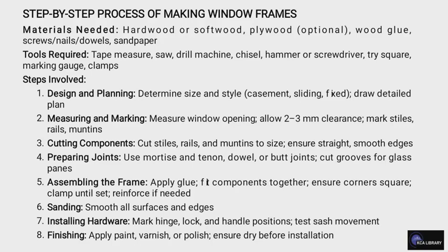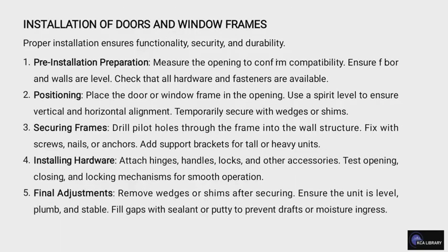Then you assemble the frame through application of glue, fitting components together and ensuring corners are square, clamping until set and reinforcing if necessary. Then the sanding comes up, where you smooth the surfaces, and then the installation of hardware comes in, marking hinge, lock, and handle positions. And the last one is finishing, where you apply paint, varnish, and polish.